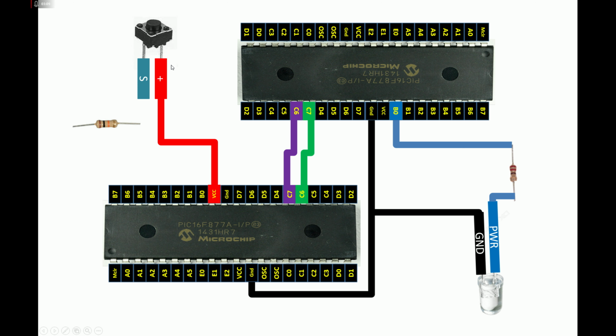You give like 5 volt to this. For the other pin, that is the signal pin, you connect it to one end of the 10K resistor like this. From the other end of this 10K resistor, you send it to the common ground. Now from the first end, where we connected the signal pin, you will take out your output. For the output, you may use any available GPIO pin. I'm going to use pin number B5 of the transmitter PIC. So this is the transmitter PIC, this is the receiver PIC, like this.